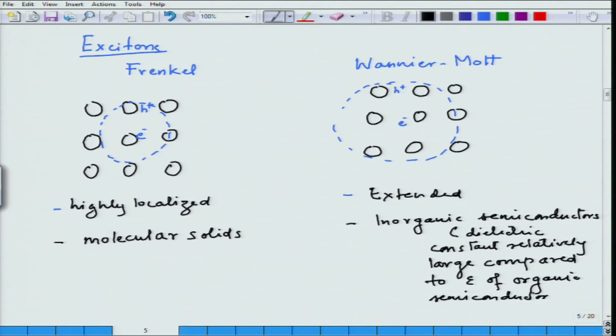This leads to the excitons being much more tightly bound in the organic semiconductor, and hence this is a problem which we did not discuss in the case of inorganic solar cells. In organic solar cells, one of the challenges is to dissociate the excitons so that we can have free electrons and holes, and then before recombining they get collected by the two electrodes.